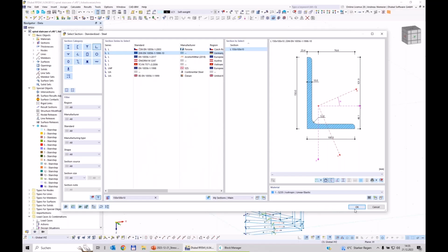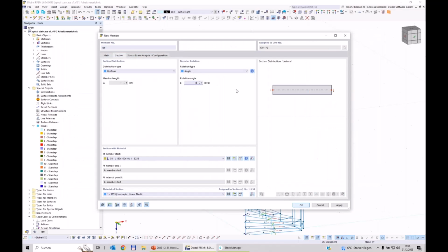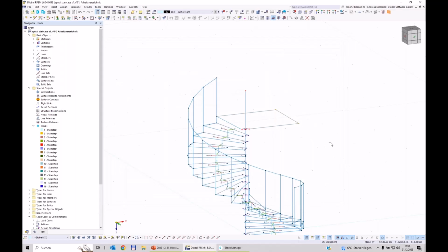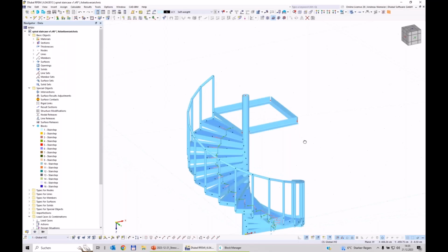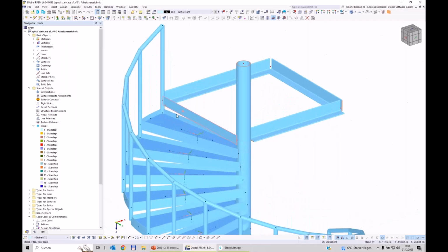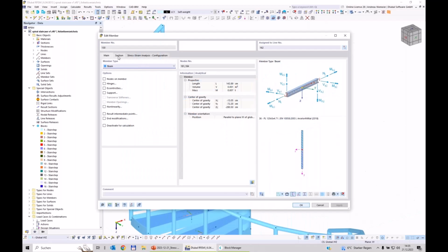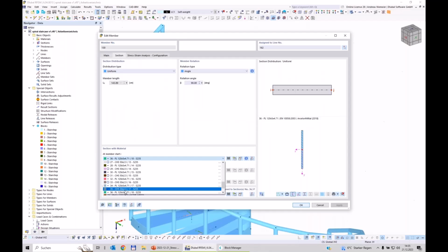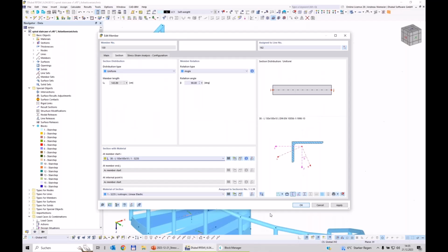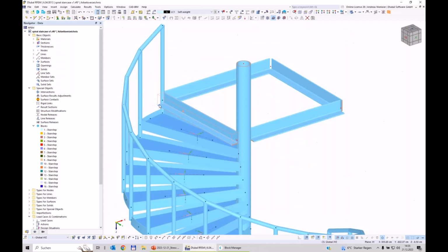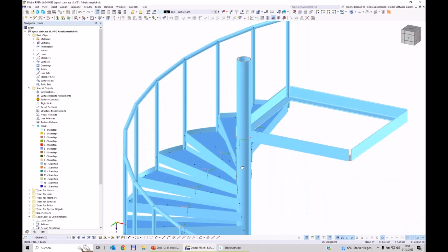And from this steel, and now we can remove this rotation, and these lines get blue. You see, maybe this front member we can change also to the same section. It should be here, this L section. But the flange should show inside, so we can take both and reverse orientation. And now it fits almost.